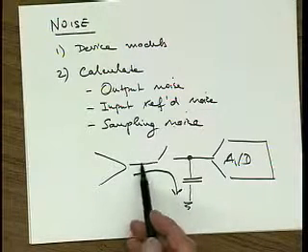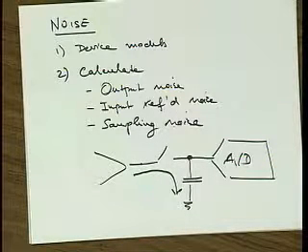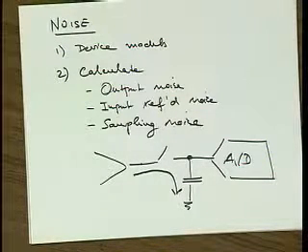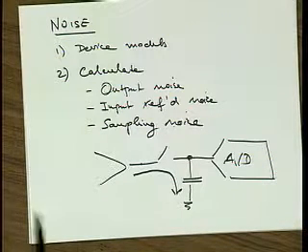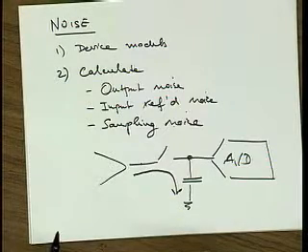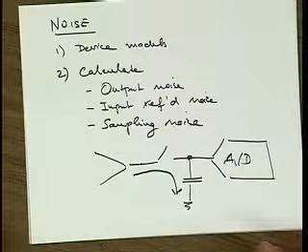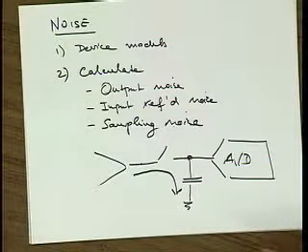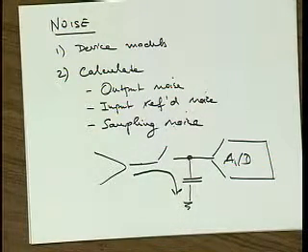Now, when the noise is here, and then of course it's this broadband woozy kind of stuff on the scope, once the noise is here, then it's a sample. It's a few microvolts, right? And whenever we open the switch, we can go with the voltmeter and figure out how many microvolts it was. It's going to be random, but it doesn't have any more this notion of continuous change with time, right?